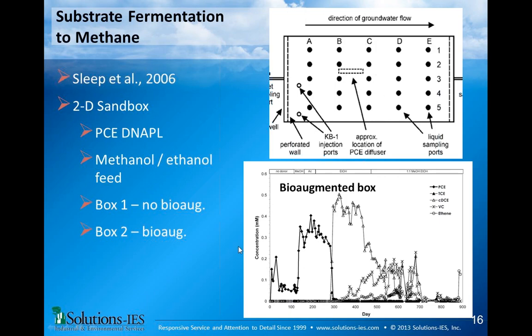Basically, the column is discharging 6,000 to 8,000 micromolar of TCE. You can see down here a little tiny bit of DCE coming out. What they attributed that to is that, as the experiment went on, you dissolve away some of the TCE from the inlet of the column. So they started getting some degradation at the very, very inlet of the column, where there really wasn't much TCE anymore because it had dissolved away. But in the really neat DNAPL zone, they really got nothing.